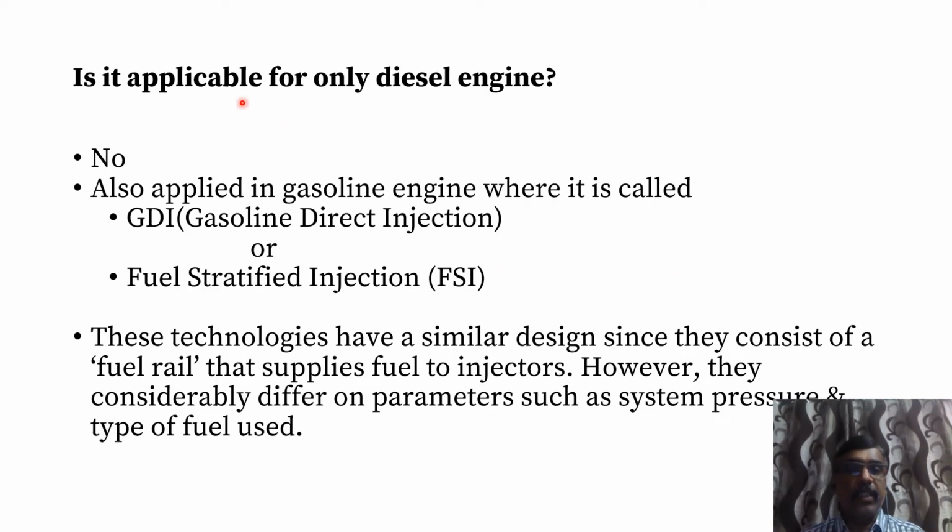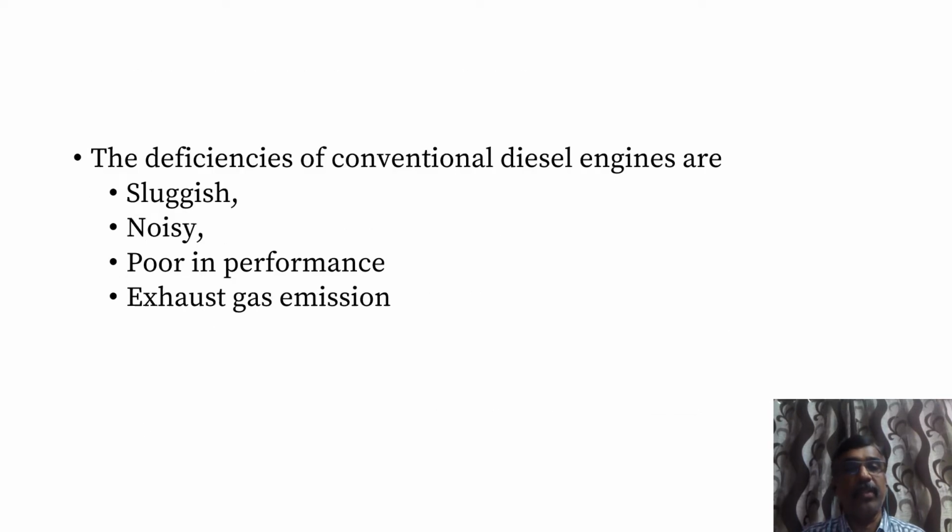Now see here, is it applicable only for diesel engine? No, it is also applicable in the gasoline engine, where we call it GDI, meaning gasoline direct injection, or normally fuel stratified injection systems. These technologies have a similar design since they consist of a fuel rail that supplies the fuel injectors. However, they considerably differ on parameters such as system pressure and the types of injectors.